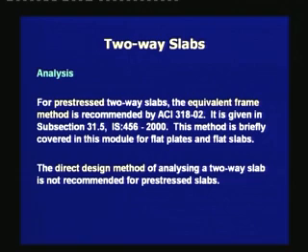It is given in section 31.5 of IS 456-2000. This method is briefly covered in this module for flat plates and flat slabs. The direct design method of analyzing a two-way slab is not recommended for prestressed slabs.